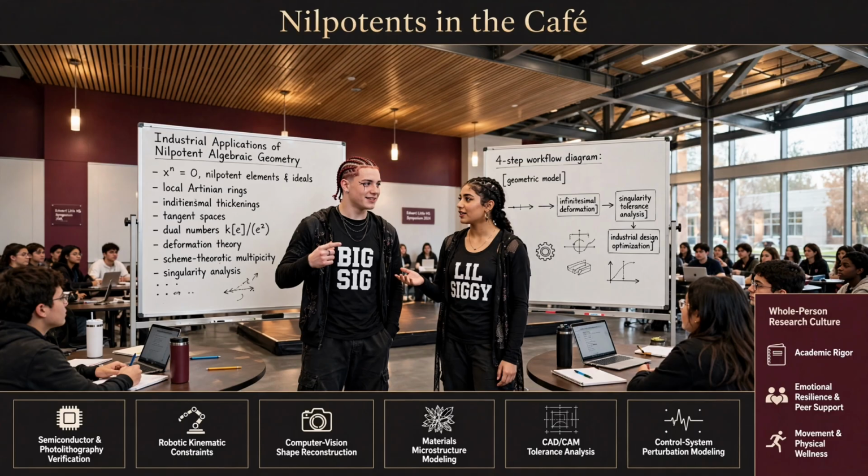Exactly. The linear software model looks at the car and says, you want to move 2 feet to the left. Error. Movement impossible. Command rejected. Classical linear control simply gives up. But in physical reality, these systems are controllable. I mean, you can parallel park your car into a tight space. Right. The controllability doesn't come from straight lines. It comes from the Lie brackets of the control vector fields.